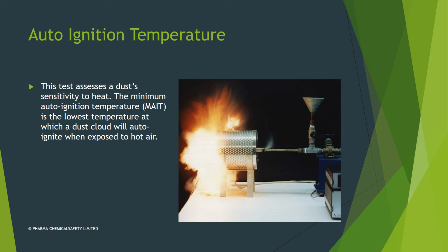Another one is the auto ignition temperature. It's to assess the lowest temperature at which the dust cloud will auto ignite when exposed to hot air. There are many processes where you use hot air. So you control everything, and now it can auto ignite as well because you are reaching that auto ignition temperature.